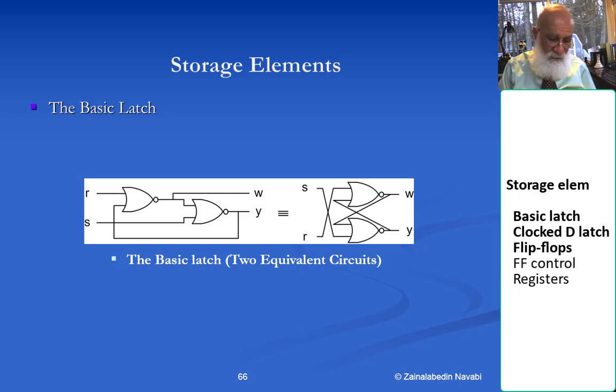Well, you can very clearly see here that the decision made on the output, let's say if this is the output, or even this is the output, the value that comes on the output of the circuit is a function not only of this and this input here, but it is also a function of the previous outputs coming to the circuit by a feedback.